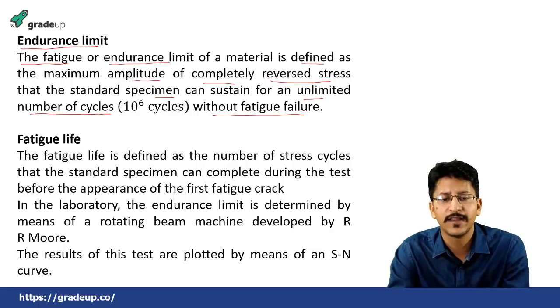Because when a material or a component is under cyclic loading, there will be some stress amplitude, and the maximum value of that stress amplitude that a material can withstand while undergoing cyclic loading for an unlimited number of cycles without any fatigue failure is known as the endurance limit.